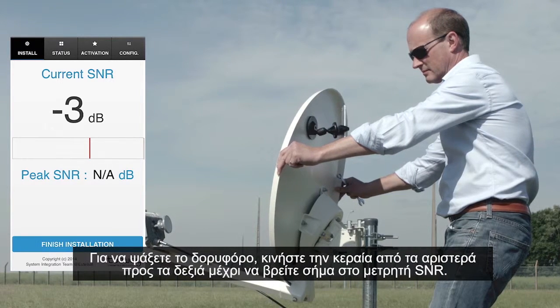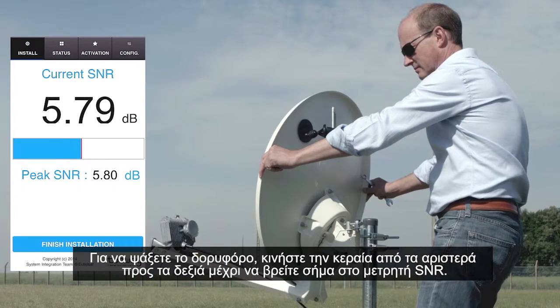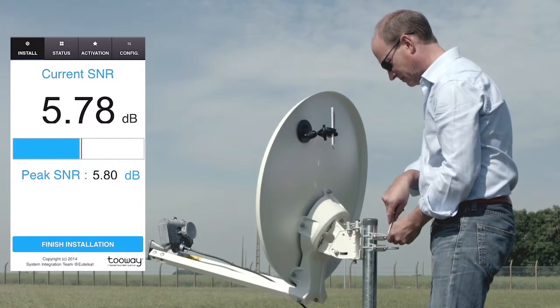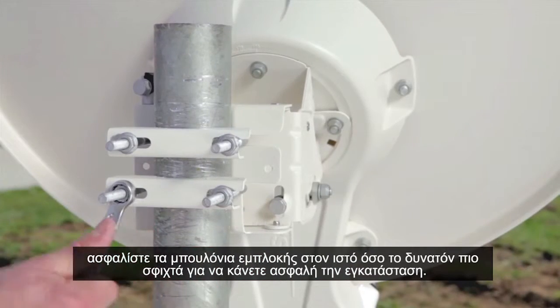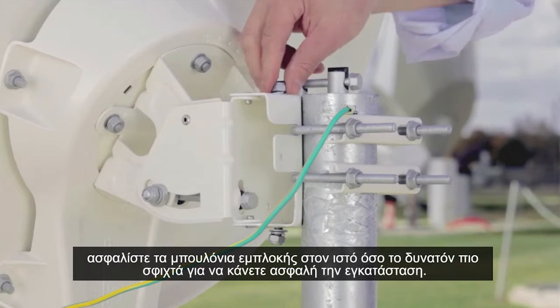To search for the satellite, move the antenna from left to right until you find a signal on the SNR meter. Once you have found the satellite, lock off the clamp bolts on your mast as tight as possible for a secure installation.